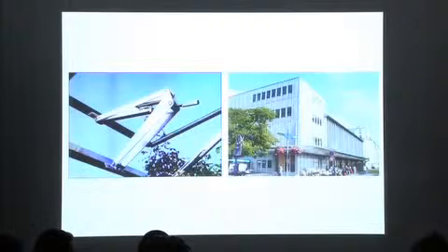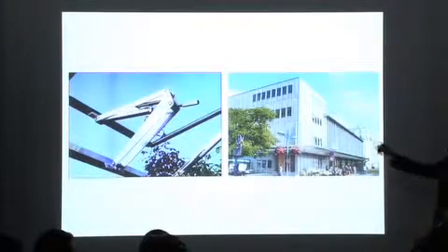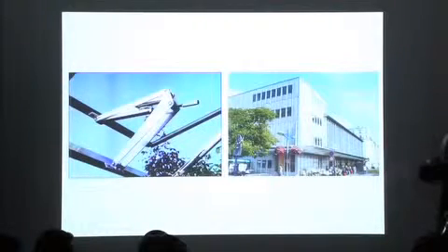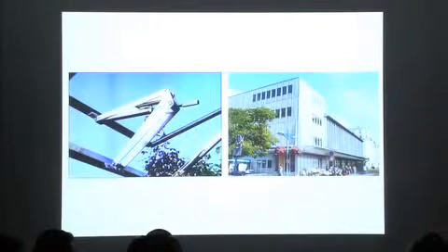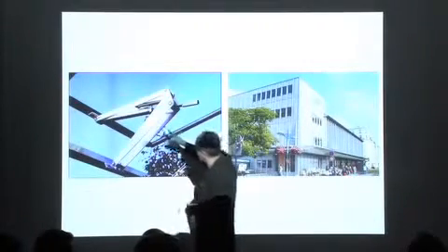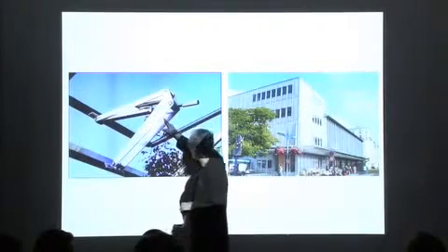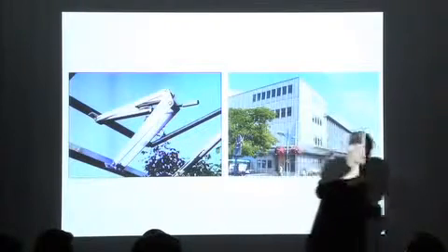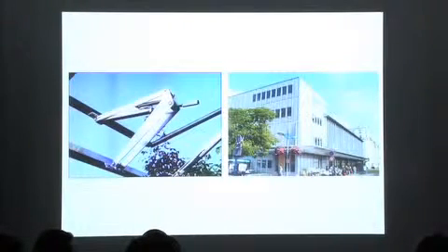Here are some quite old-fashioned control devices. Wax-actuated ventilation, which has been used since Victorian times in greenhouses. I don't think that's actually a wax. It might be. I think in this tube you have wax. So when it gets too hot, the wax melts, the tube opens up, the window opens, you get air into the greenhouse. Immediate response mechanism. That's been around for a long, long time.